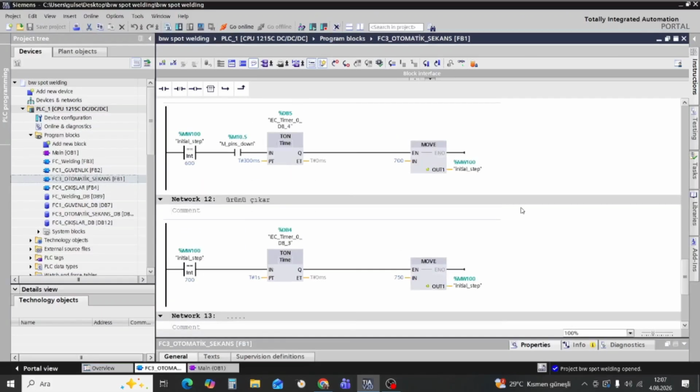Sometimes when the part is outside the sensor's detection area, a small part of it can still be in the station and is about to leave, but not completely. To overcome this, it is suggested to put a timer on.